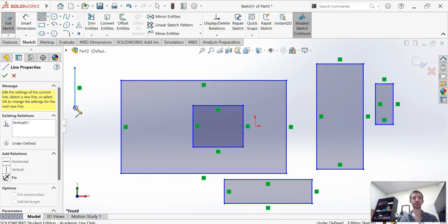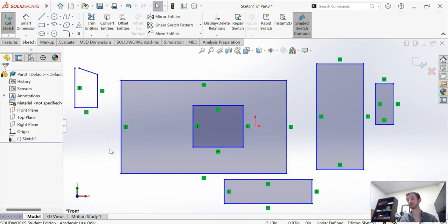Like if I draw a rectangle using some lines, that's almost closed. Not quite closed, almost closed. This is closed, this is not closed. If you have what's called a contour, that's a set of lines that make a complete closed shape, it will fill it in. It'll color it in and say, hey, this one's closed. If it's open, where it's just a set of lines and it doesn't actually connect all the way around, it will not color it in. This is important for later on when we begin taking these 2D sketches and turning them into 3D models.